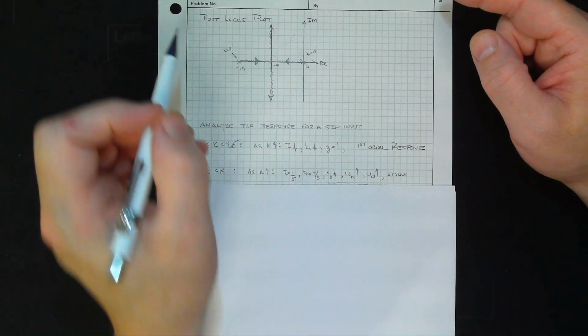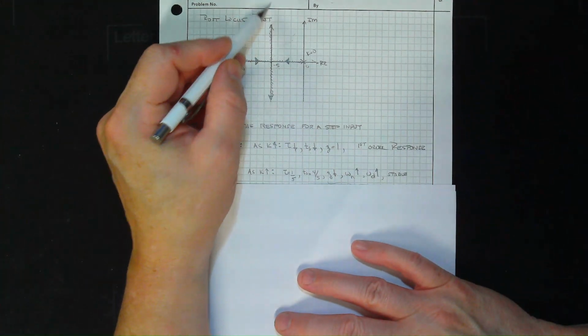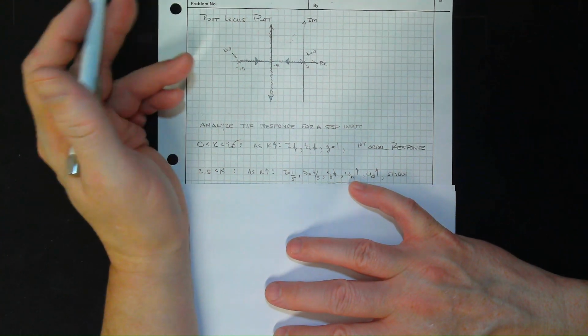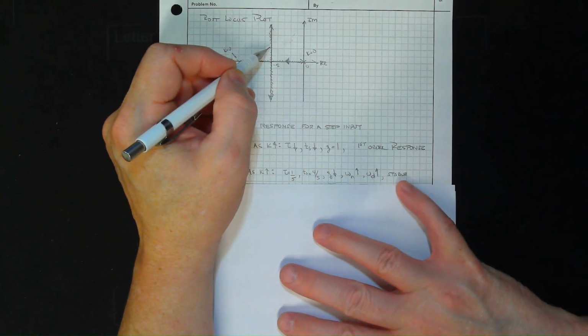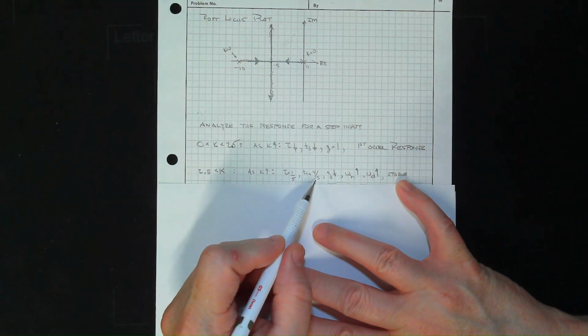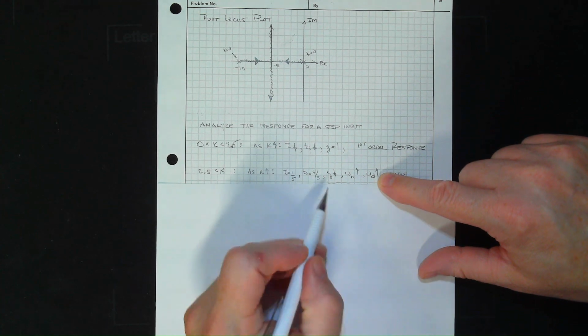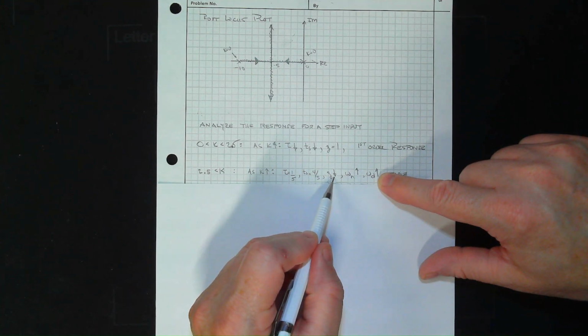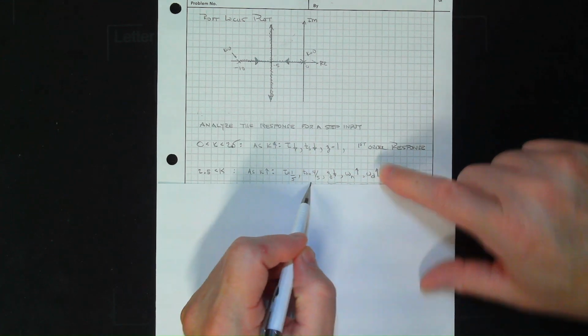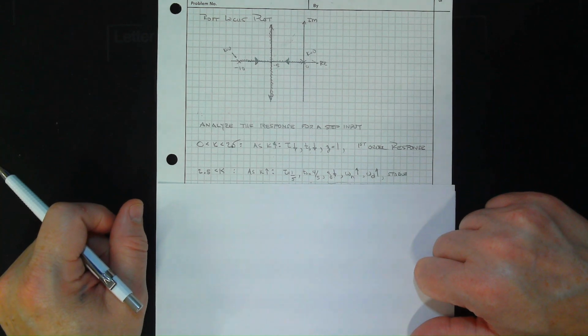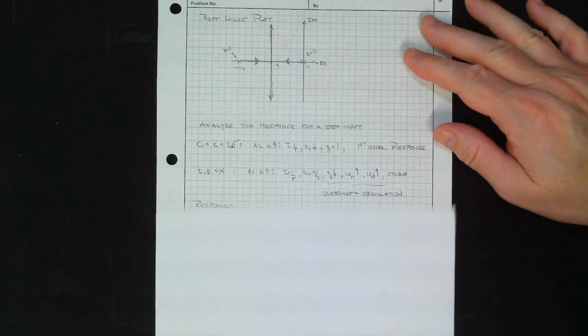All right. But here's the interesting thing. K can get as big as you want. You can make natural frequency as big as you want, but it always stays stable. It's still going to settle out at the exact same time. Your frequency could be getting very high with wild oscillation because your damping's low, but it's still going to settle at 4/5 of a second, no matter what you do. It's kind of cool.